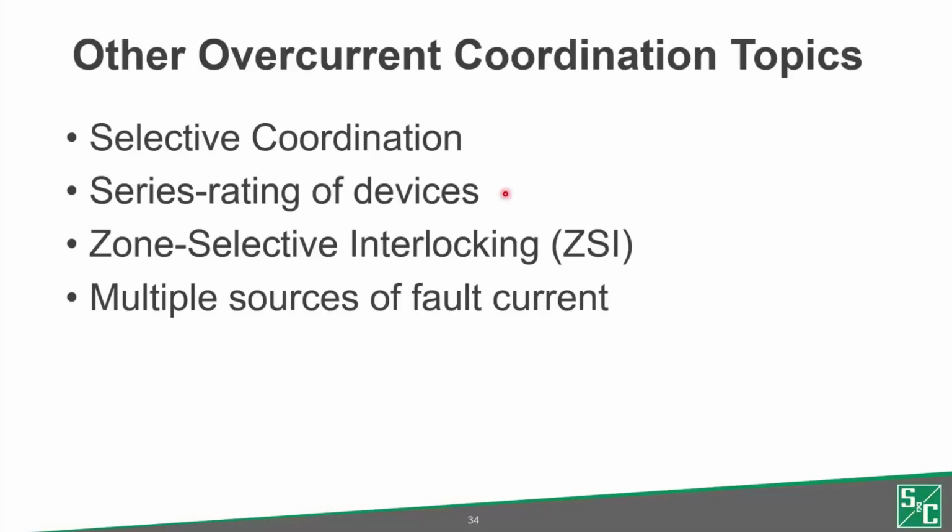If you've got a 10 kA rated panel, but you want to apply it in a higher fault rated system, you could get series rated circuit breakers or fuses that will protect that panel appropriately, but it takes a bit more engineering to do that.